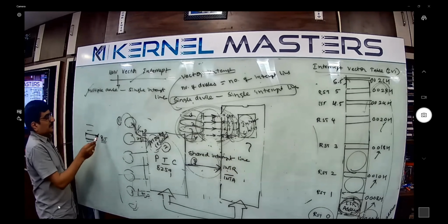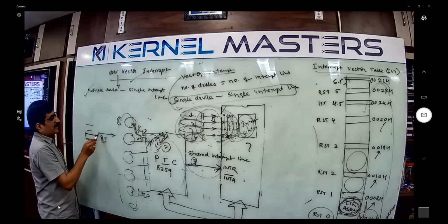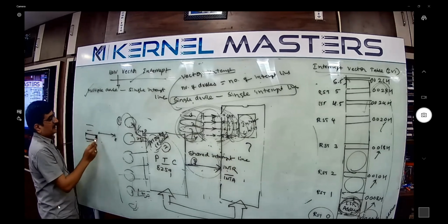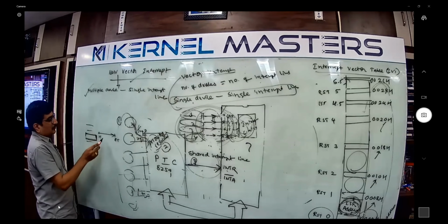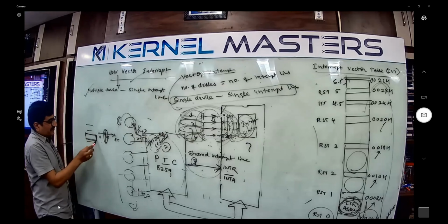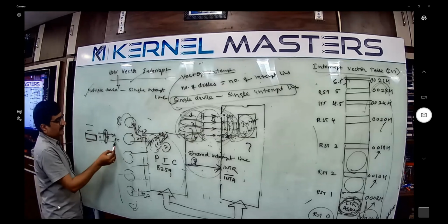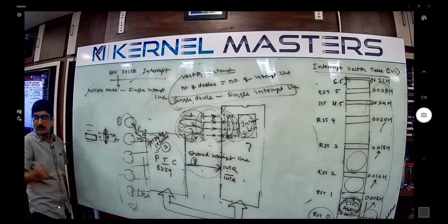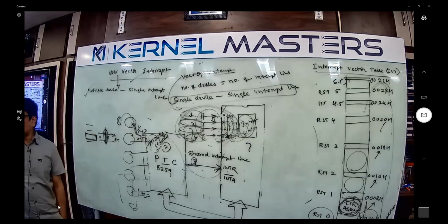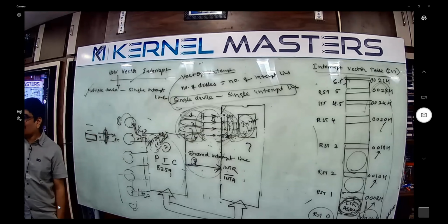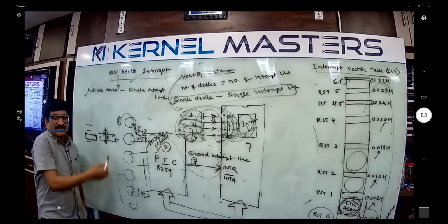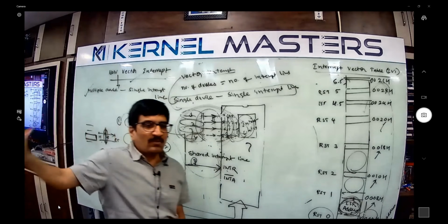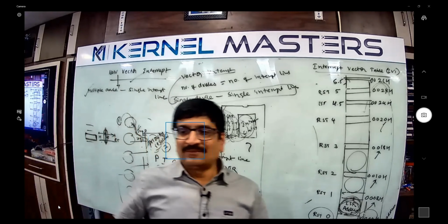How much time does the instruction take? 8 cycles. But exactly at the 4th clock cycle, the interrupt occurs. The microprocessor cannot handle it, because it is already in the middle of the instruction. Only after all 8 cycles complete can the instruction close.